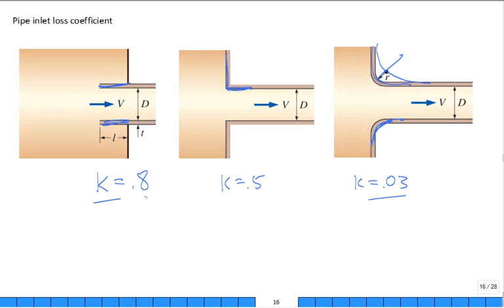Why is this loss coefficient even larger than this one? Just try and get the most extreme fluid packet, and it's going to have to come around right there, and it's going to have the most severe change, probably a larger recirculation region. It separates, a larger separation zone, and that gives you the larger loss. Here, if you're just helping the flow go around the bend, much better.